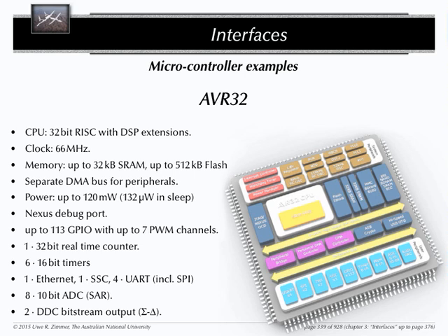113 GPIOs, standing short for general purpose I/O pins. You will play a lot with GPIOs later on, because ultimately everything you do inside of your chip has to be connected to one of your GPIOs. Hence these GPIOs today have to be so flexible, because you handle analog signals there, you handle different forms of electrical connections there. This can all be freely configured with the same set of IOs. Having GPIOs in the hundreds is quite standard these days. You actually have multiple hundred for more modern machines.